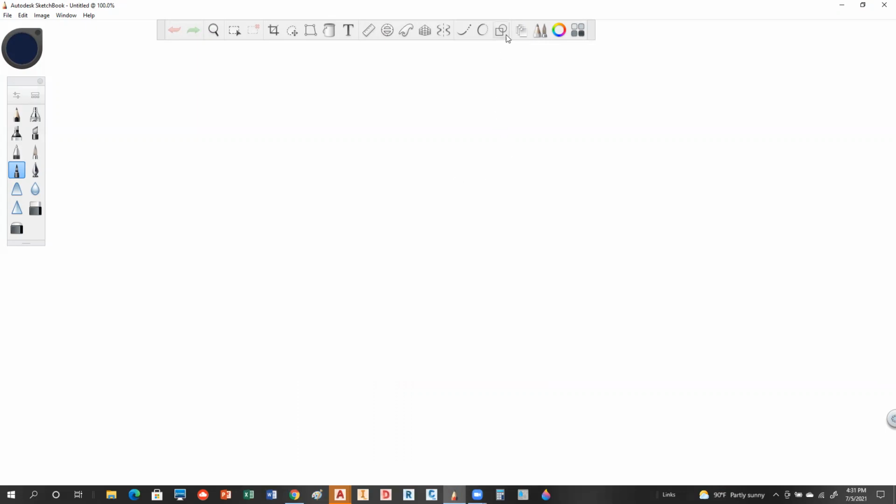But based on what we just showed here, let's say I'm going to draw something very similar to this. I've got this, and then I've got this. So there's my little flag. So when I rotate this thing, okay, what I'm going to do first is select the objects that I want to rotate. So in this case, I would select those 3 or 4 objects. After you hit enter, then it's going to ask you for a base point. Now, the base point can be literally anywhere, but think of this as like you're sticking a pin at this point, and that's going to be the point of rotation. So when I ask for a base point, I might, let's say, choose that point.